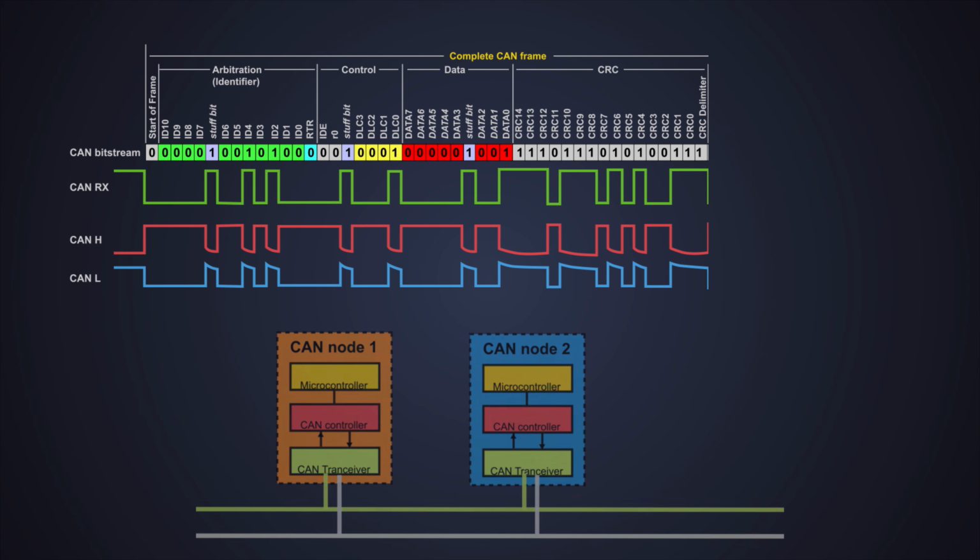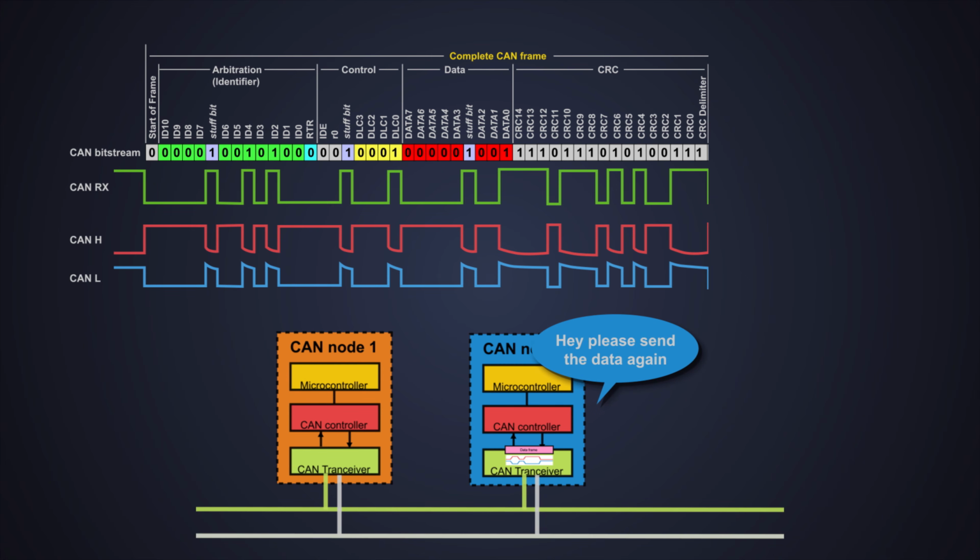A form check basically checks whether the CAN frame sent or received is in a standard frame format. The CAN frame format must be maintained throughout the communication. The receiver checks for the delimiter bit after properly receiving the identifier and data. The delimiter bit must come at a predefined place so that the form of the CAN frame is maintained. If the receiver does not find the delimiter bits at a proper place, it generates a form error frame.